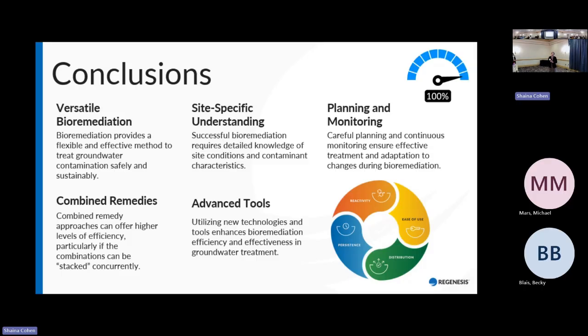And so are you doing that through soil vapor monitoring, or through actual groundwater sampling? You can do ongoing monitoring of groundwater sampling. Having a baseline is really important, though. There's always some degree of ethene, ethane, carbon dioxide and these dissolved gases that are already there. So having a good baseline is really helpful so that we can see, hopefully, that increase relatively shortly after the application. Okay, great. Thank you.